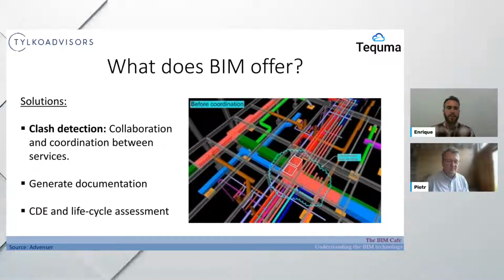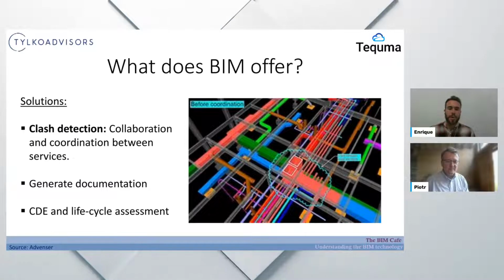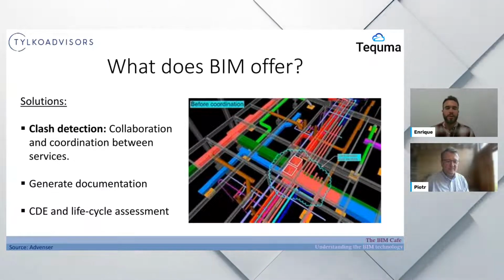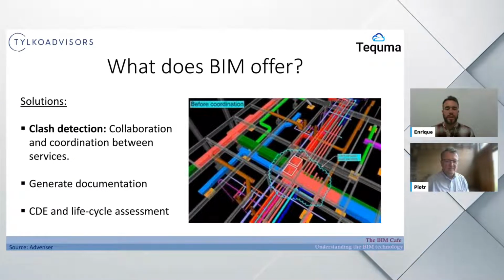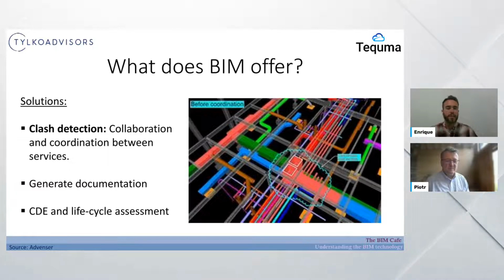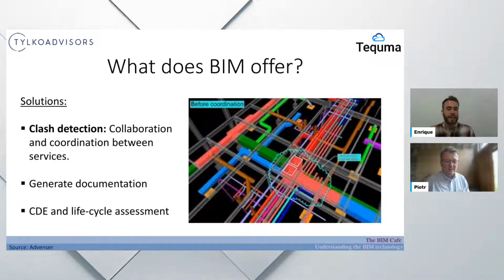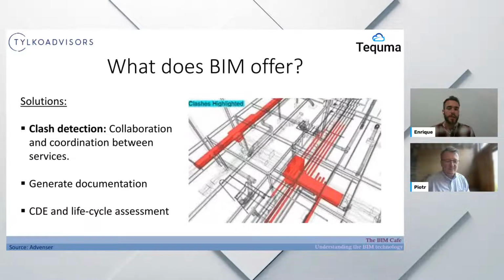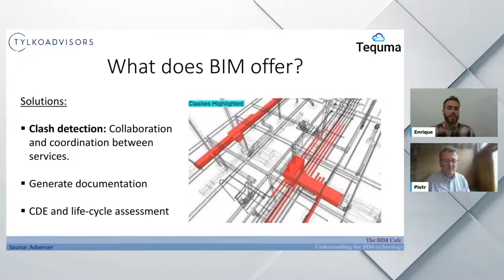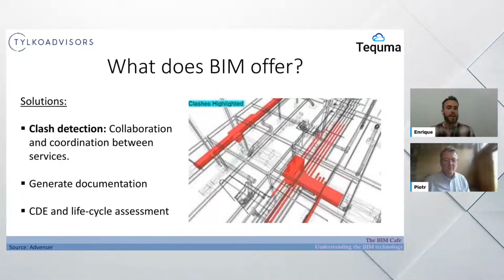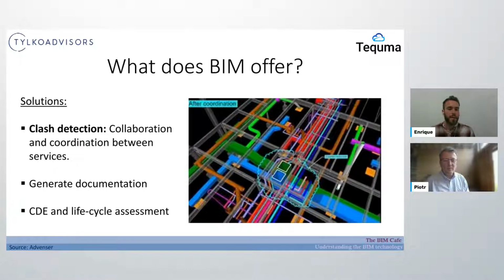Okay, you will have some requirements to go to a certain level or not, but there are places, of course, in large projects mainly, where you can find some potential clashes. And with BIM, you can see on this representation how they can even highlight the clashes. They can extract it and say, okay, these potential conduits are clashing with others, so we need to propose a solution and bring it to a stage.